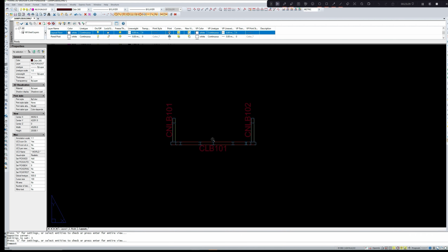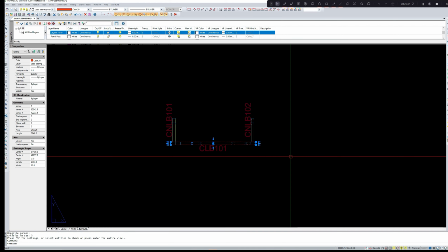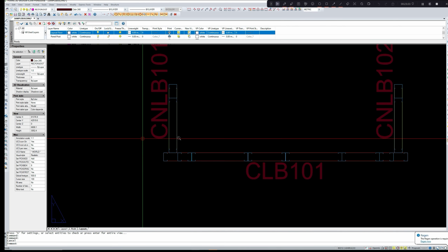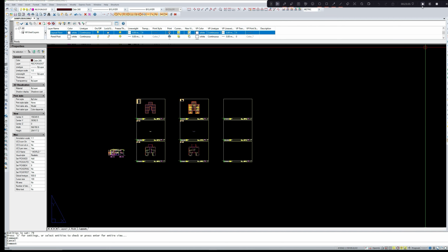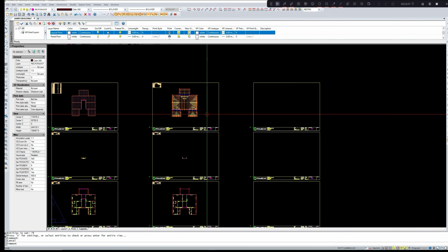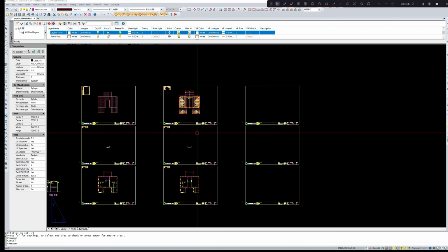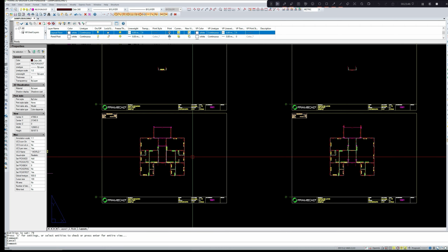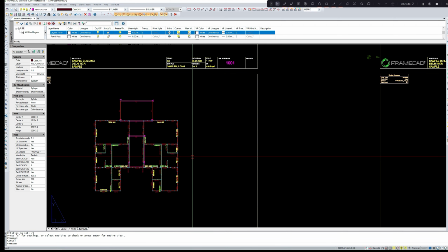So one wall is there which is not touching, so this wall is there. Okay. With this our checking of the IC command, the panel integrity check, is over. In the next section we'll insert braces to all these walls.